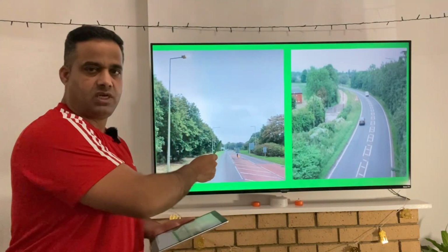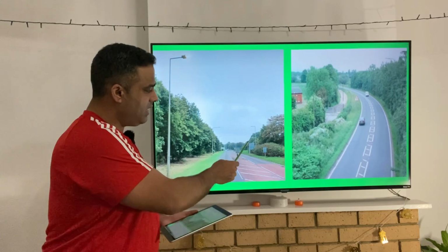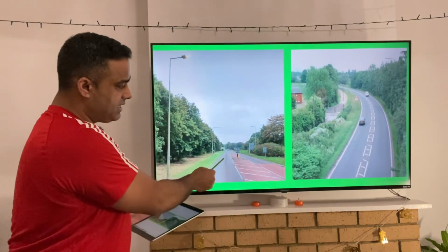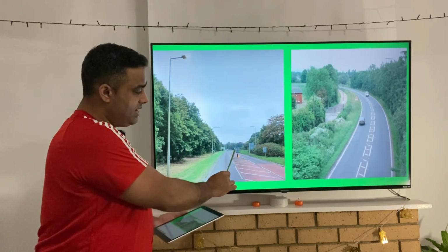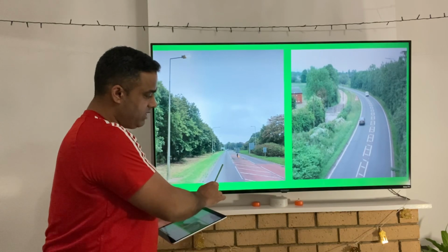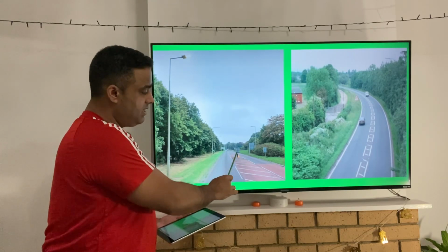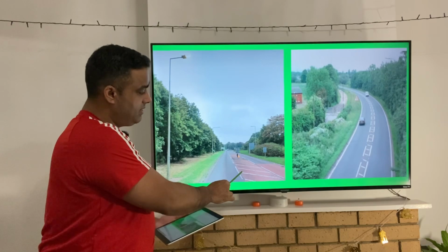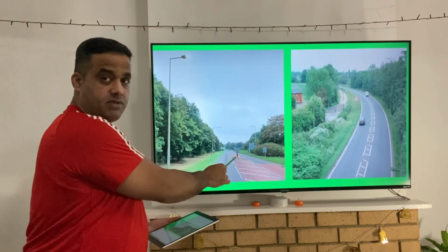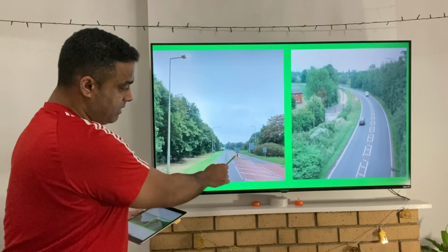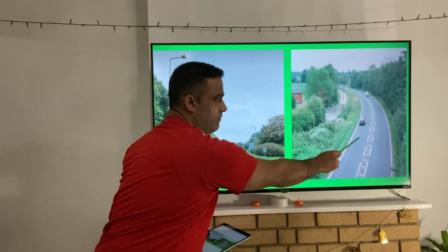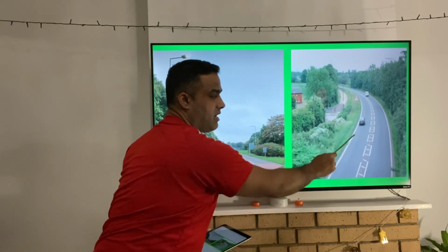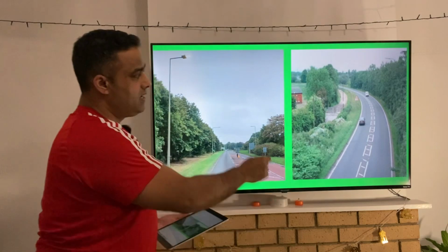Whereas if you look at this picture, as we discussed about the single carriageway, there are 2 different types of single carriageway. In this single carriageway, there's some sort of physical barrier here, but not all the way. This one has hatched markings, and some sort of bollards, some sort of boxes in the middle to tell you to keep yourself on the left side. Physically you can drive on that side, and they can come on this side as well because they are broken lines. So these are the pictures of single carriageways.